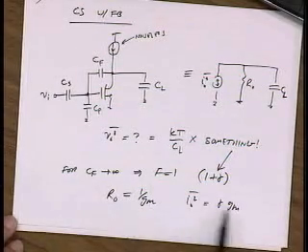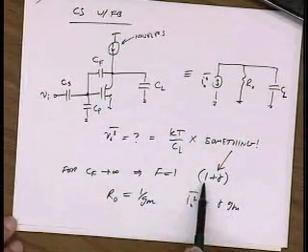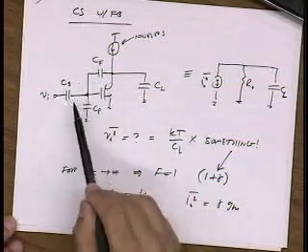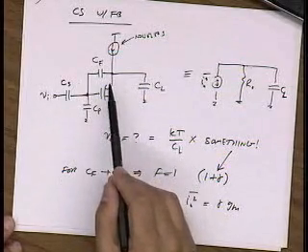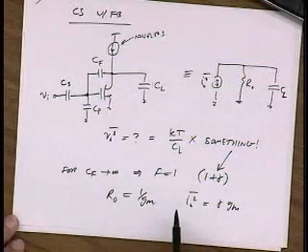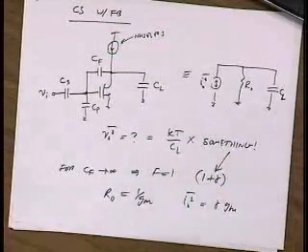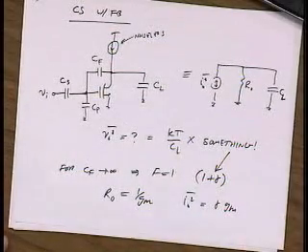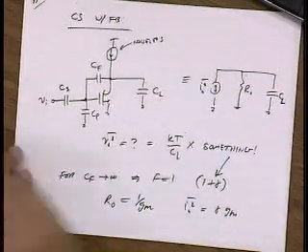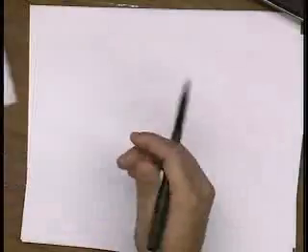This gm cancels out. Where does this extra factor of 1 come from? Well, this noise leaks into the input and makes its way back to the output. But the intuition here is that when F goes to 1, this factor is between 1 and 2. Okay, very good. So what about the general case?